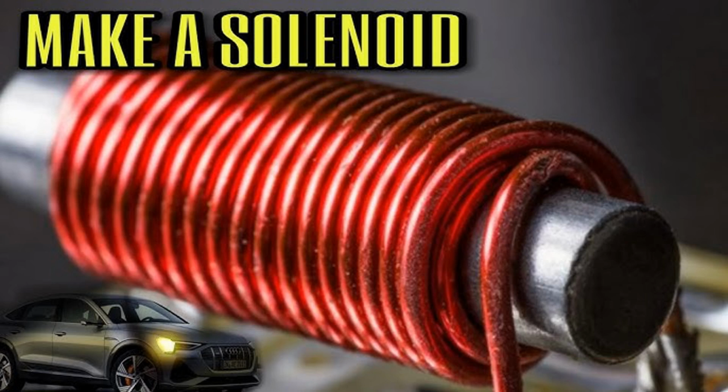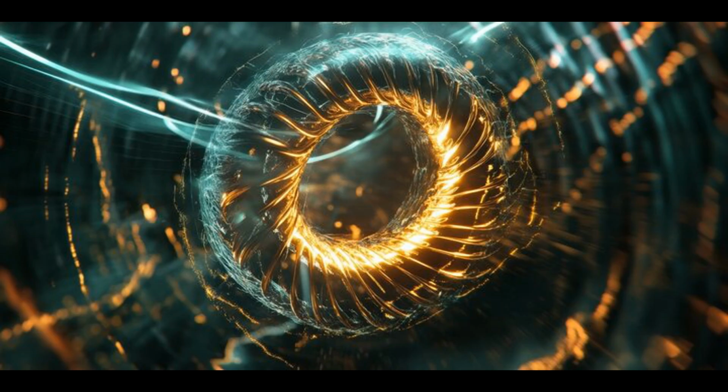7. Yoke, magnetic field concentrator. Material: made of ferromagnetic material. Function: the yoke helps direct and concentrate the magnetic field produced by the coil, improving the efficiency of the solenoid. It minimizes the leakage of the magnetic field and enhances the force applied to the core.